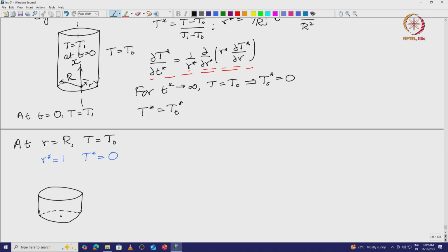So, if I plot the temperature as a function of the radial coordinate, what can it be at r is equal to 0? This is an axisymmetric configuration. That means that if the temperature field coming in one direction looks like this, the temperature from the opposite direction has to look something like this, because it is axisymmetric. In a third direction, it will look something like this, and so on, based upon the different directions in which you approach the axis of this cylinder.